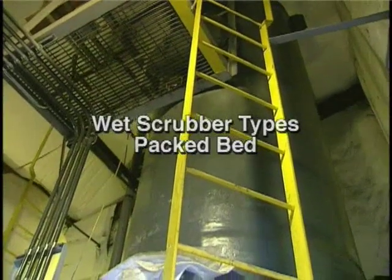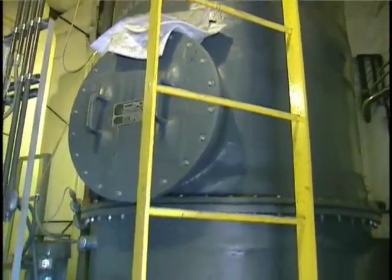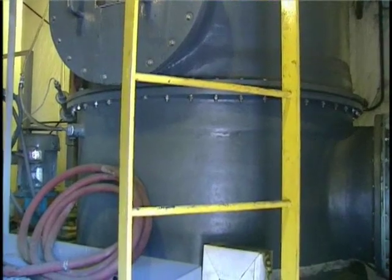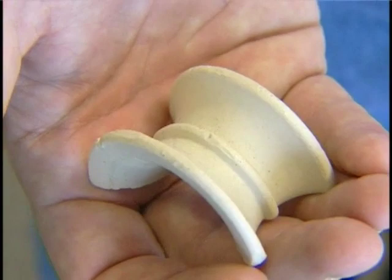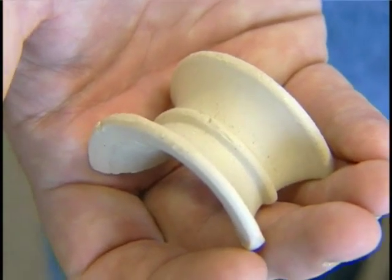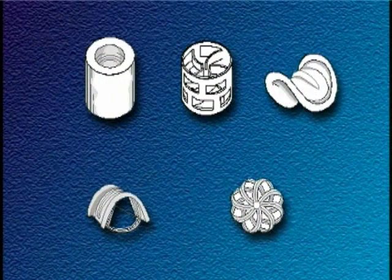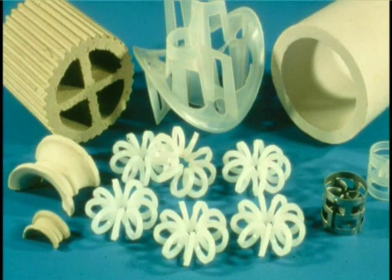Packed bed scrubbers are another type of medium-energy collector. Packed bed collectors spread the liquid over packing material in order to provide a large surface area for particle impaction. There are many designs for the packing materials, but they all have large surface area while maintaining open areas for the gas flow. Although they are usually made of plastic, metal and ceramic packings are available when plastic cannot be used.